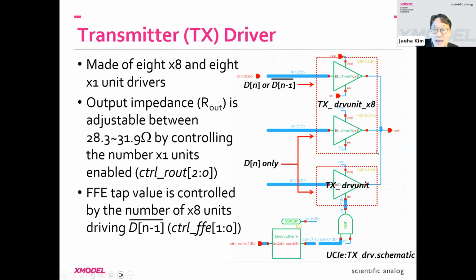And the other thing is you can control how many unit drivers are driven by the current bit, D[n], and how many are driven by the D[n-1] inverted. That way, you can control the amount of de-emphasis, basically the tap coefficient for the TX FFE.